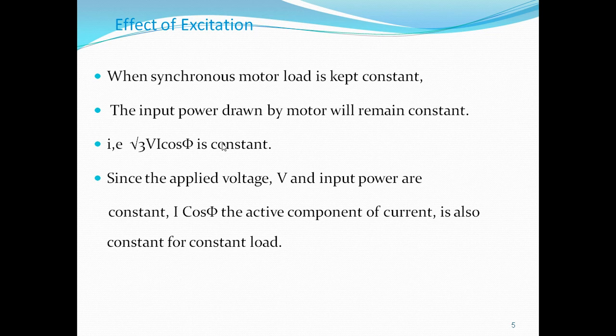How are we changing the excitation? Normal excitation. Here we will study by keeping the load constant, so the power input is also constant. If you change the excitation, then power factor changes and current changes, but the product I into cos phi is constant.